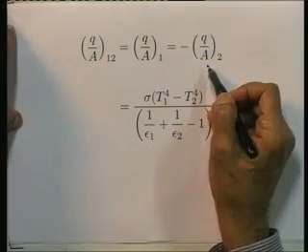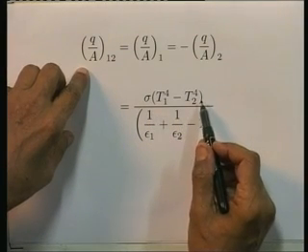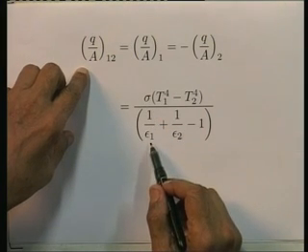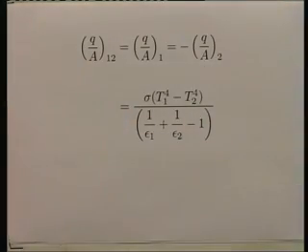Okay. Now, there are only two surfaces in this enclosure. So, if there are only two surfaces, the net radiant heat flux exchange between the two surfaces is equal in magnitude to the net radiant heat flux leaving either of the two surfaces. So, in this particular case, since there are only two surfaces involved, q by A 1 2 must be equal to q by A 1, which in turn must be equal to minus q by A 2, and that in turn is equal to sigma (T1 to the power of 4 minus T2 to the power of 4) divided by (1 by epsilon 1 plus 1 by epsilon 2 minus 1). So, this is the expression that we are looking for, the heat flux supplied at surface 1 or at surface 2.